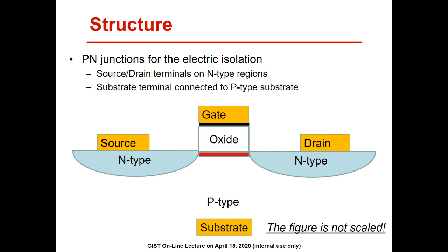The electrons move from the lowly biased terminal to the highly biased terminal. Therefore, the lowly biased terminal acts as a source of electrons. On the other hand, the highly biased terminal carries away the electrons just like a drain. In this sense, they are called source and drain respectively. They have identical structures.